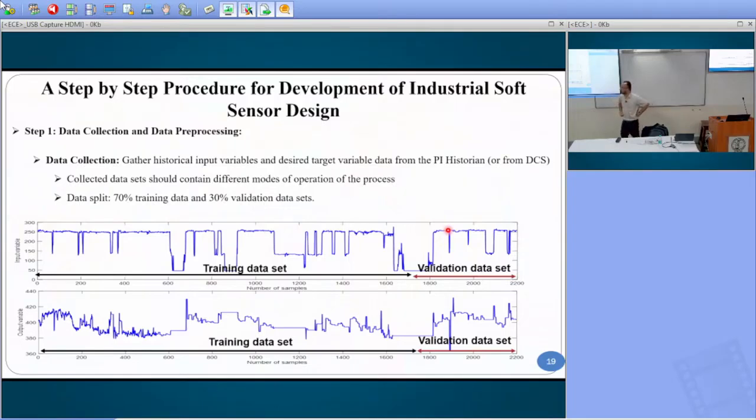It varies a lot. You can identify that there are some outliers over here. They last significantly long. Maybe the sensor has gone; it drops immediately from 250 to 50 degrees, or whatever the temperature or flow rate is. Because it's for a longer time, it's not a normal process change, it can be an abnormal change, a sudden drop in your flow rate. Maybe the sensor is malfunctioning and not giving the result fine. But there are some other spikes.